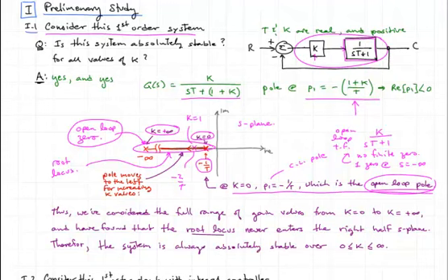It's the locus of roots of the denominator as we vary this parameter k, this gain in our system. I should mention that in general you can vary any one of a number of parameters in your system, though oftentimes it will be simply a k that would be in the numerator of your controller, such as kp or ki over s or kd times s, those kind of terms.